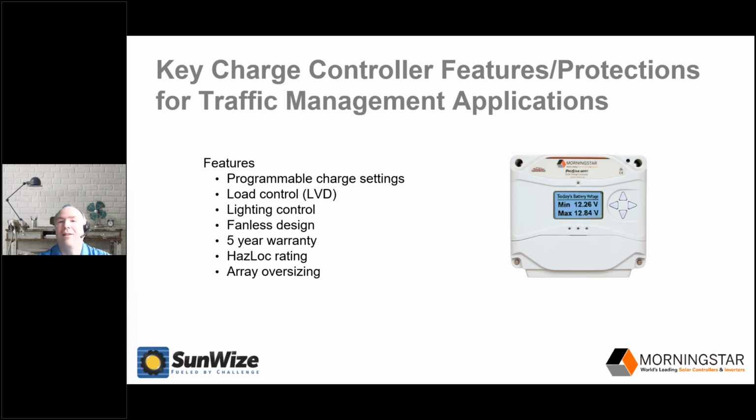Some controllers have load control, otherwise known as low voltage disconnect or LVD. This feature disconnects the battery from electrical loads when a battery's voltage dips below a set threshold. This is important if you want to make sure that your batteries don't over discharge, which can kill batteries and render them useless over a short period of time.